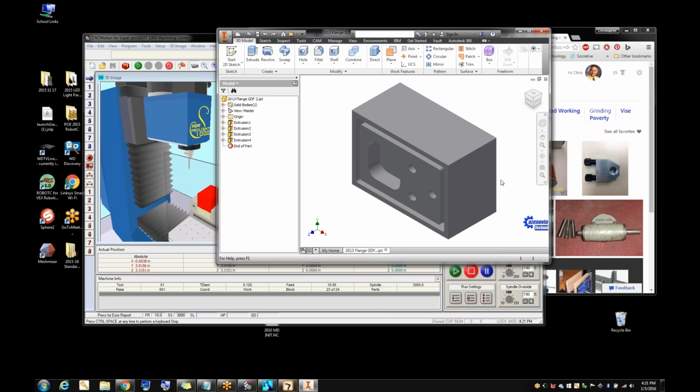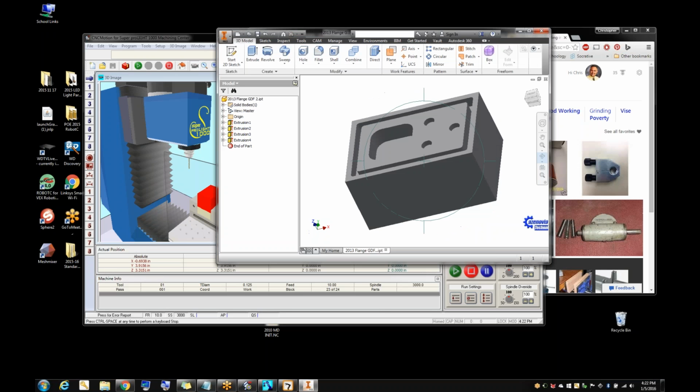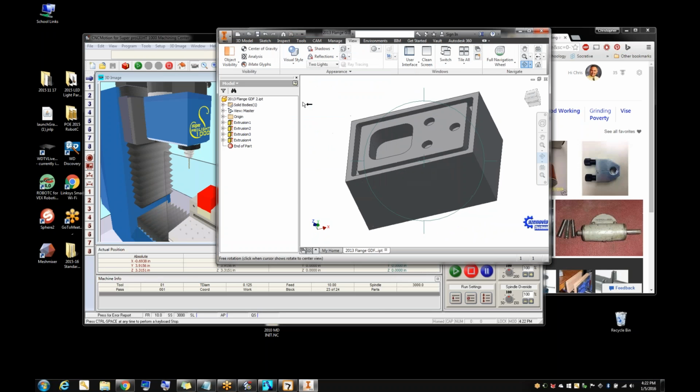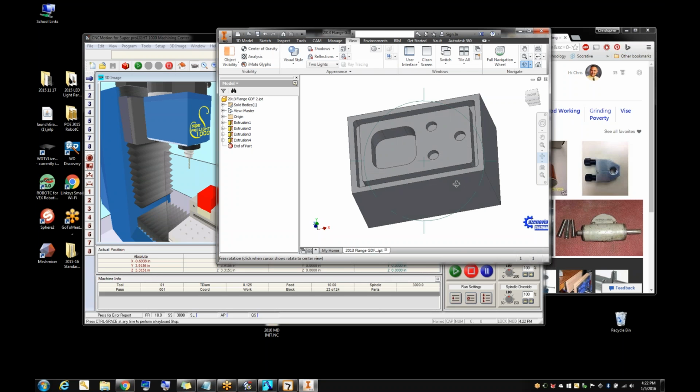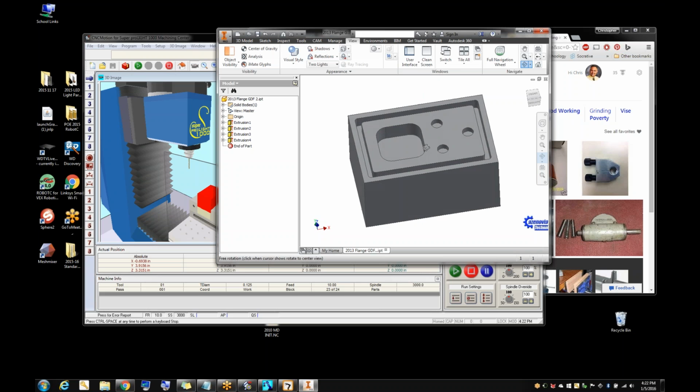The biggest problem with the flange is that next time you take care of that path around the outside. That path around the outside, we have found that HSM does not like to plunge. It always wants to either ramp into it, or it wants to do a helix into it. There are a couple different strategies built into it. So if you don't go through and actually change a couple of the settings, it'll always dig into the part. I think that's exactly what's happening. It's not plunging straight down. It's kind of lowering as it moves in. Yeah, it's designed that way. They don't like the philosophy of full engagement on the bottom of the tool as it goes into the part. That's just HSM on its own.